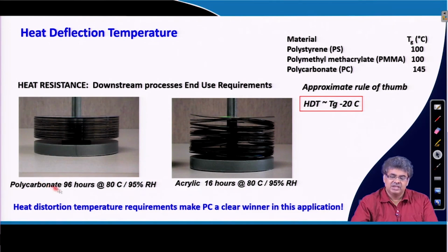So, basically we should know the value of Tg and Tm for a semicrystalline polymer, but we should also keep in mind the final application, and depending upon that we may need to use other thermal measurements like HDT, and others such as the Vicat softening temperature.